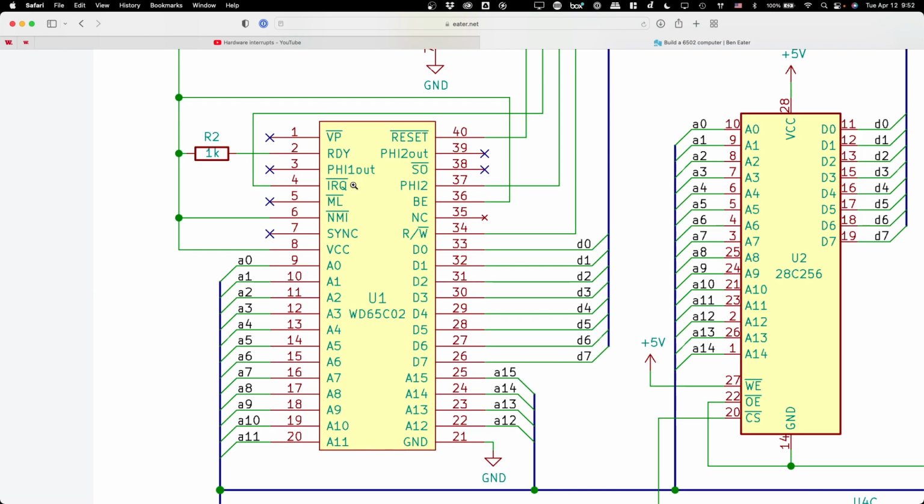The second thing it does is it takes its current value of the program counter and its current value of the flags register, and it pushes them onto the stack. That makes sense because when we want to return to executing things the way that we were, we need to know where were we when the interrupt occurred and what were the flags when the interrupt occurred so that we can reset those just before we go back and resume execution.